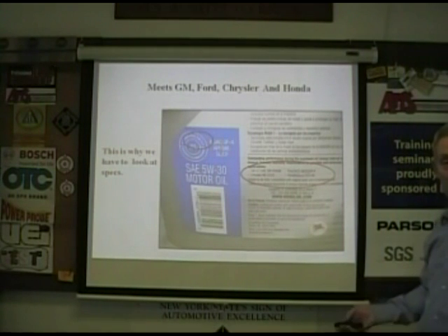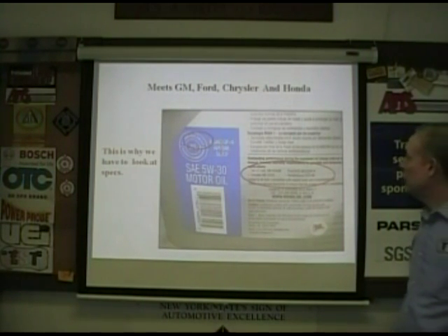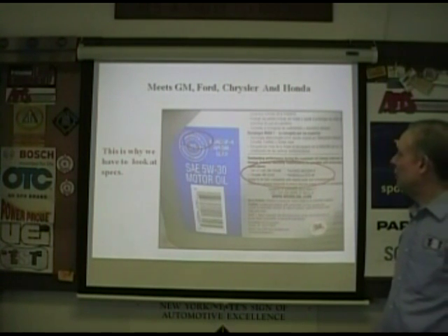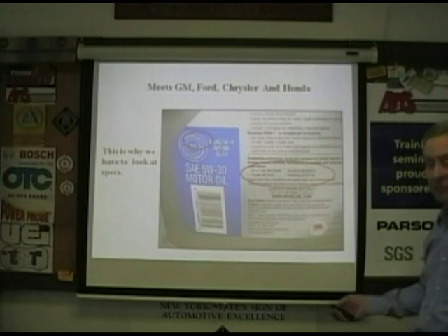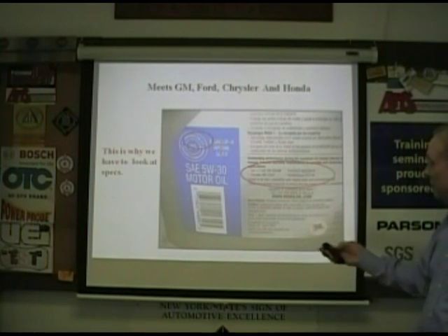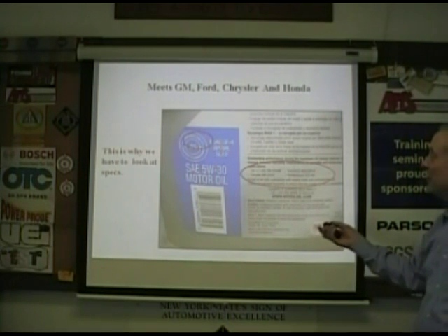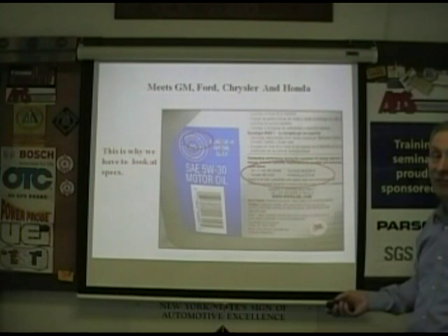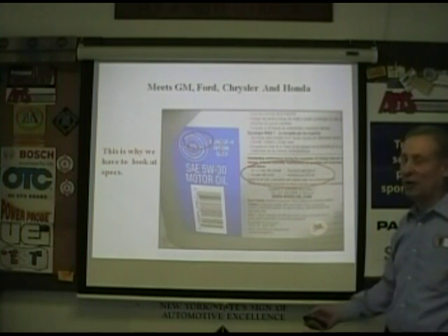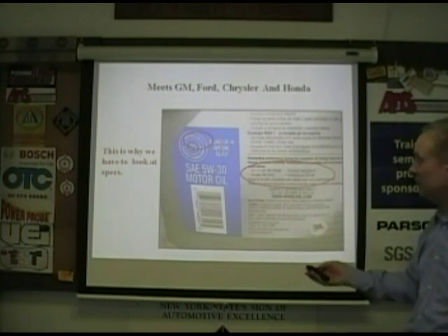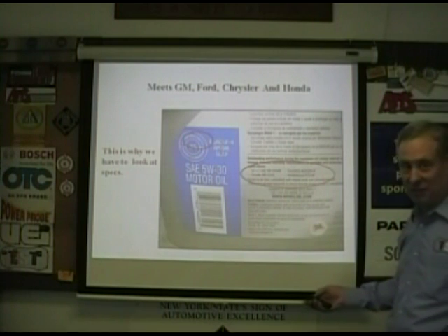I have a question, Pierre. That ILSAC GF4, is that the highest spec? No, that's not the highest spec anymore. We have GF5 now. Thank you. But it was the spec on that. Now, there was some documentation recently that some GF5 oils have been rated GF4 only because they didn't have enough labels for the new stuff. You have to go by the label. You can't trust that they meet the higher spec, because somebody told you that.